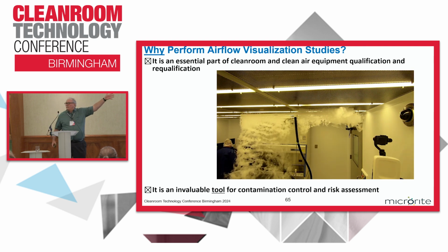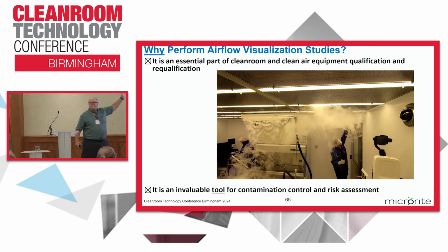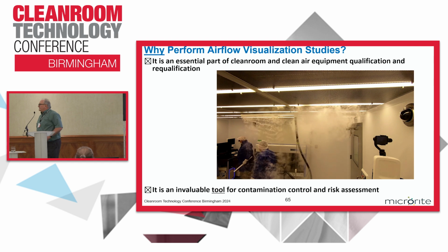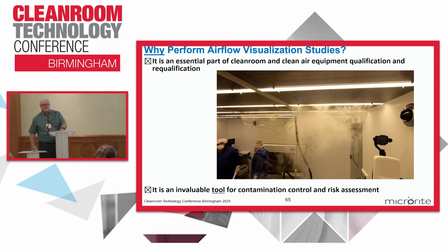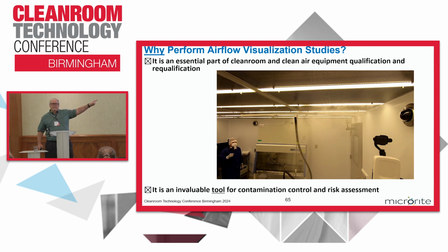This clean room was qualified. The certifiers were there the week before we came in to do the study, yet one of the filters was off. They leak tested all the HEPA filters. They tested air velocity, supposedly, and they may have. Again, something could have happened between when we came and when they did their testing. Don't know. But the most important point is the end user had no idea they had this problem.